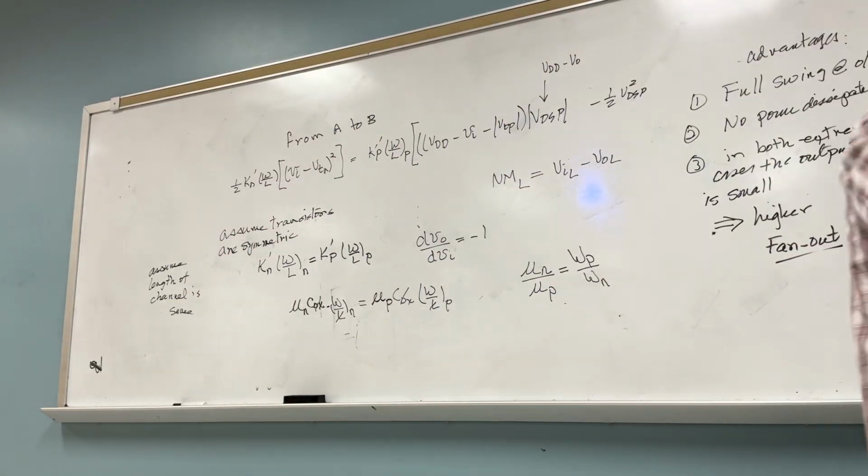So how do we size the transistors? How do we choose this W and the L? Did you get it or not? Okay. I want you to answer me the following question. Who is faster, electrons or the holes? Electrons are faster, which means what? Mu N is much larger than mu P, which means what does it tell you about the width of the channel? The width of the channel of the PMOS needs to be wider than the width of the channel in the NMOS. Did you get it? For the two transistors to be what?